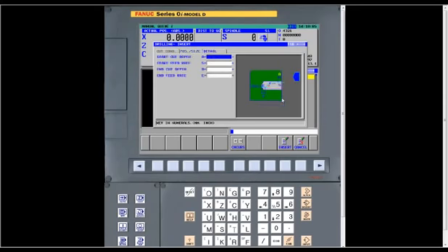So that's very simple. Then it also has detail data. And again, all four of these have asterisks next to them, so you do not always have to answer that information. But what this detail is, say you had a very large drill and you wanted to start it out at a much slower feed rate than what you would actually want once it got fully engaged. That's what this is for, to where you can start out at a slower feed rate and then increasingly make it faster. So that's what a drill cycle looks like.